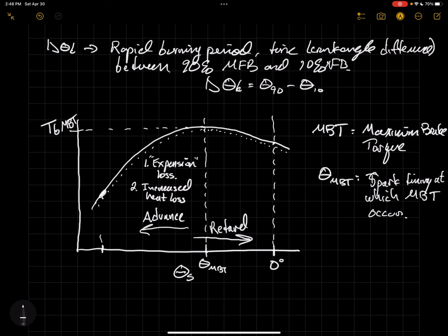And so you have increasing pressures due to compression, but also increasing pressures and temperatures due to combustion. Particularly those increased temperatures drive a higher heat transfer rate, which at this point, of course, is going to be a heat loss. And the increased heat loss will cause you to have less energy available for transfer to mechanical work, which necessarily means a lower torque, okay?